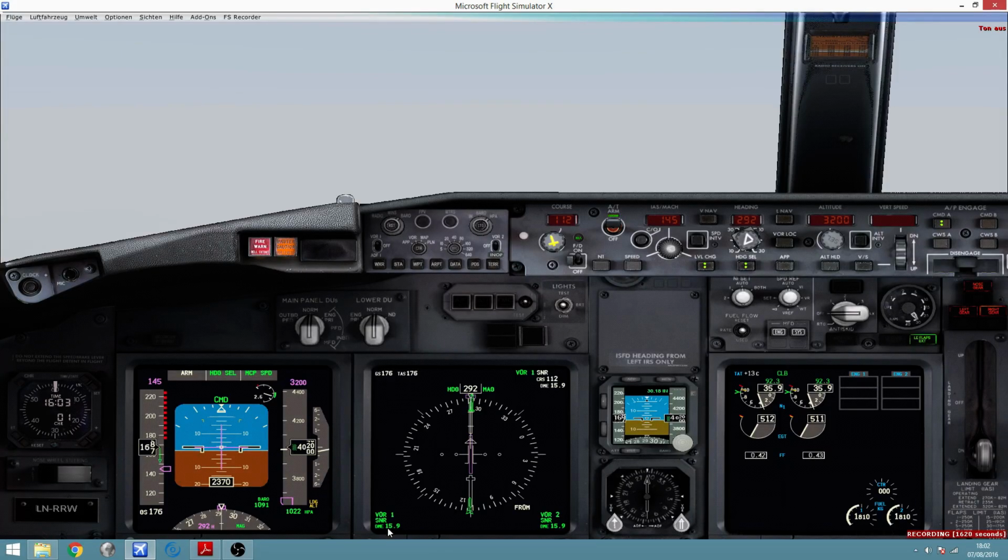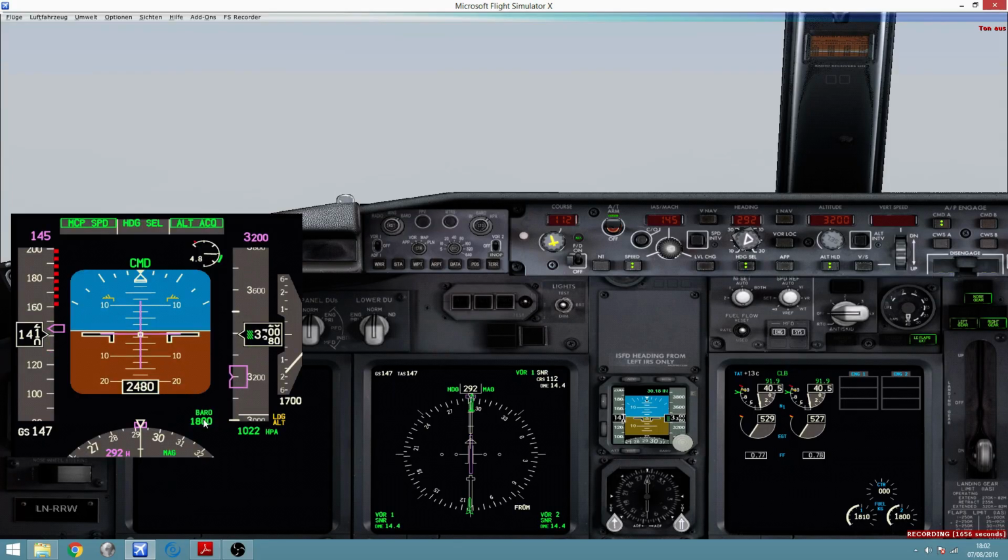good. So I haven't reached yet 11 DME from Sierra November Romeo. Remember, I was still missing the Baro, the minima selection. So I will select 1,800. It's a very high minima, that's why it's taking me so long to select it. You can read it on the primary flight display, how I'm changing it. It's going through 1,700, and I'm about to reach, good. So now I've reached 1,800.